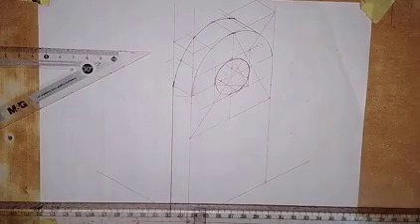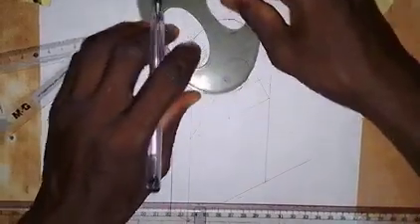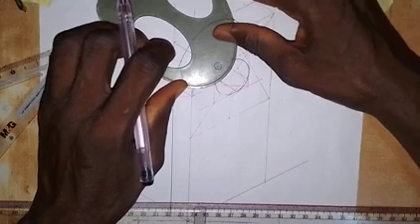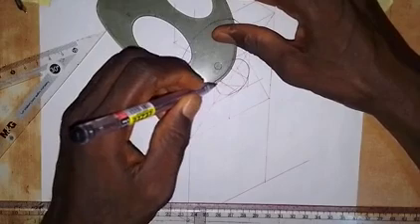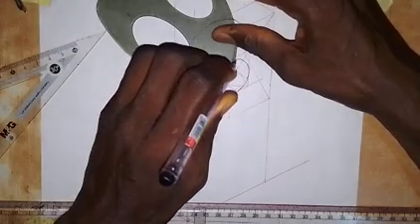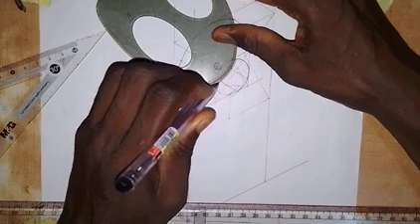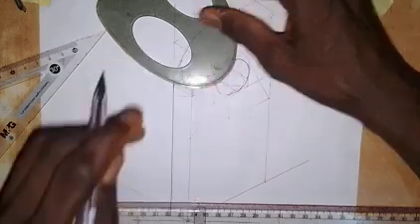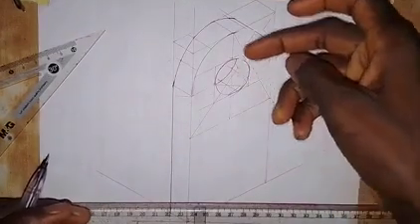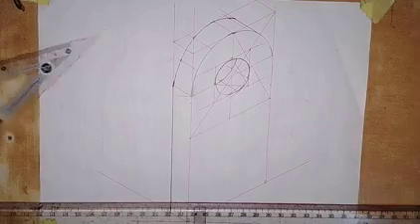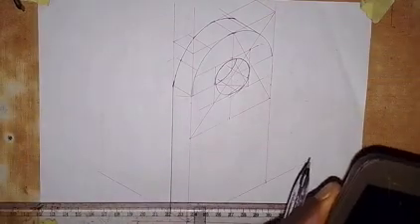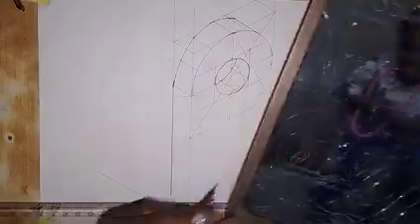This is how it goes. With this French curve here, I'm going to set it like this. Okay, just make sure you set it very well like this. Then draw this curve like this. Okay, so this shows that we can see the other part of the hole. So this is how it should be. We still have some other things to do here.